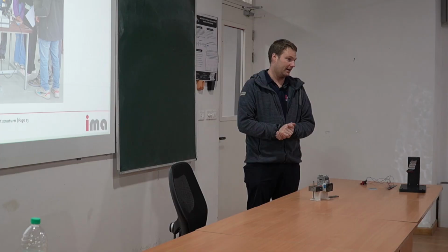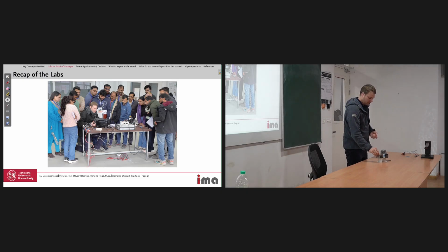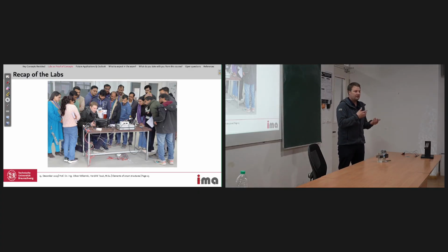Yes, and then in the second lab we did the butterfly hysteresis. I guess you remember the butterfly hysteresis. In the lab we determined the butterfly hysteresis experimentally as elongation over the excitation voltage. And this you can calculate into a displacement, and from the displacement you can determine the strain. So what we had in the lecture was strain over field, and the field you can also get from the excitation voltage by dividing it by the distance between the electrodes. Okay, so this was our second experiment.